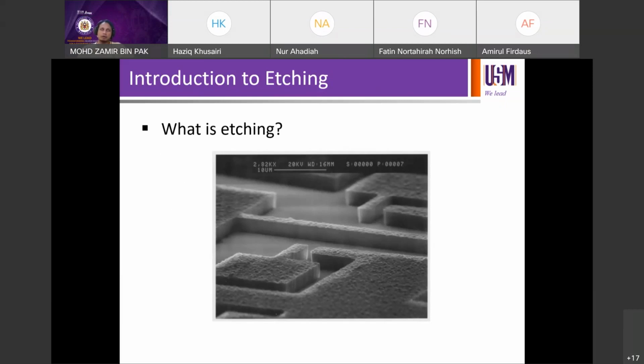Before this, when we talked about lithography, we discussed up to the patterning of the resist. So that means when you open the resist, you etch the resist that is soluble, whether it's positive or negative, you open the area and then you'll get something like this, for example. So let's assume this high area is all resist. Okay, let's just assume this.